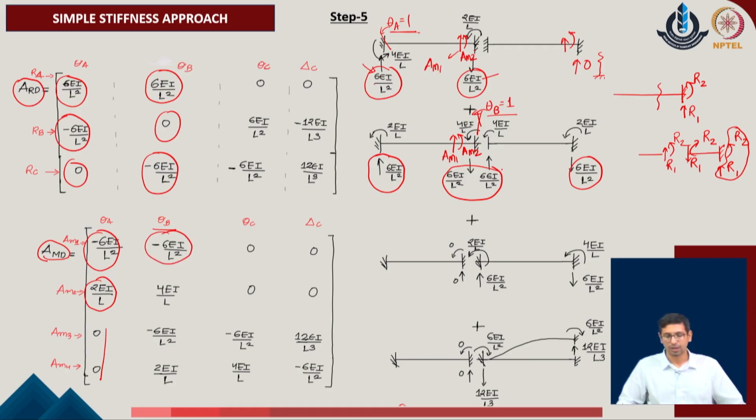One must also note that when we are calculating R of B, we are taking the net resultant of the total reaction which is appearing at the joint B, which is the contribution of the member AB as well as member BC of the given system. But when we are calculating the member forces, member force contribution is only defined individual to each member of the given system. So, AM1 contribution will only take into account the first component of the reaction force, whereas when we move to the AM2, in that component this particular part or its equilibrium condition over here will be evaluated.